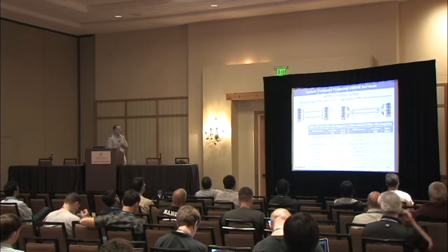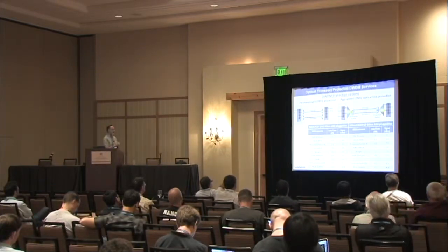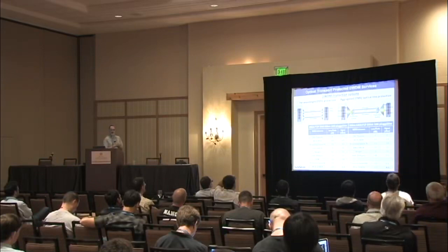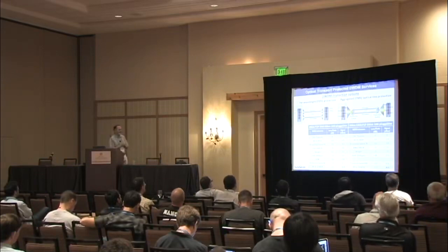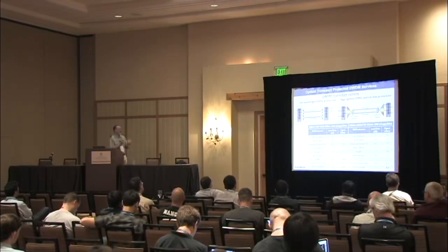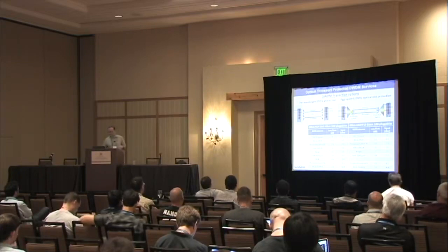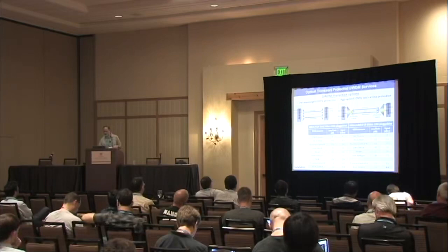So we are good. We can do the same using the 80 kilometers, and the only difference is that we don't need any dispersion compensation, so that line is blank, and I'm coming in at minus 8. So again, within the active range of the receiver, we are good. Again, in these cases, it's theoretically possible to do the 40 kilometer. I personally prefer the 80 kilometer option.